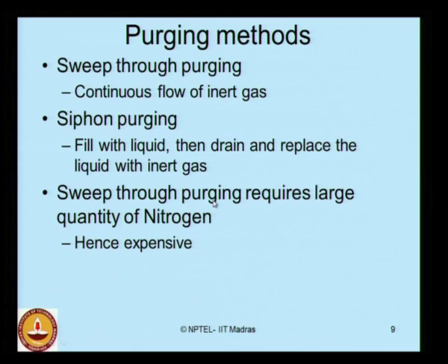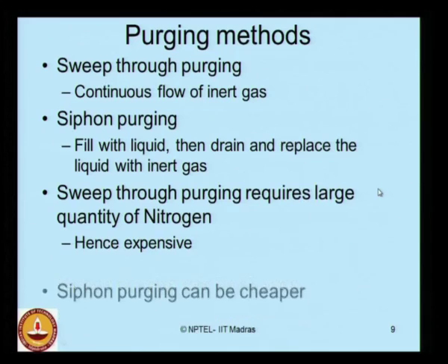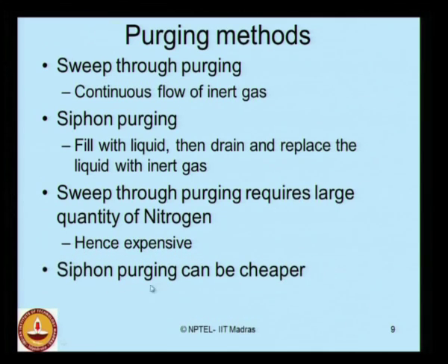Sweep through purging requires a large quantity of nitrogen, and hence this is considered to be a very expensive process, and it is commonly not practiced in the petroleum industries. Siphon purging rather could be cheaper in comparison to sweep through purging.